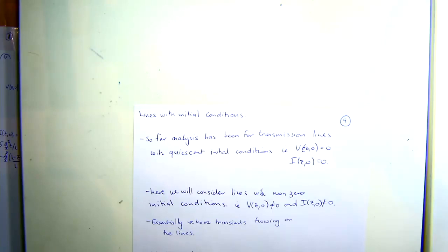All right, so you charge this line, you leave it for a second, and it goes to 10 kV, essentially 10,000 volts. So you've got to choose the right transmission line and the right coaxial cable. And then at some time, you close that switch, right? So what happens? Because this is very high impedance, you can almost approximate it as an open circuit. The voltage across this transmission line goes through the impedance,